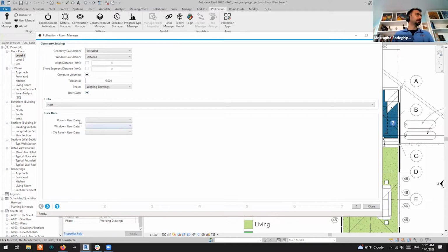The way to do that is then you can go, and for curtain wall panels, for example, write them in your comments, and then we export the comment with every curtain panel that we export. And then in Rhino, or we had a recipe on Pollination, we can pick up that user data and based on that, assign a logic to that object. Does it make sense? I remember you wanted something to remove some of the rooms. You can just go and add a comment on remove, and then have a script that looks it up and says, whatever has a comment removed, just remove it from the model. Something like that.